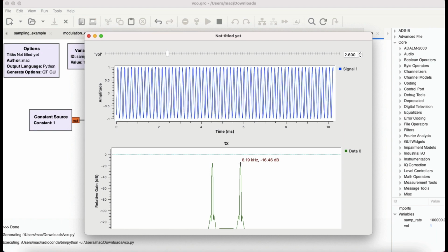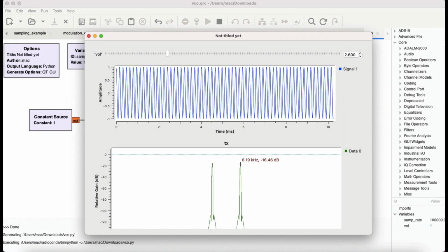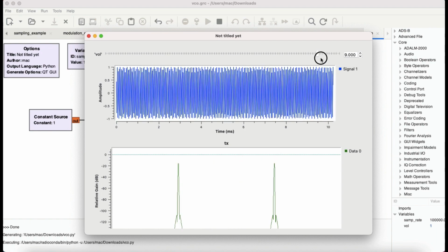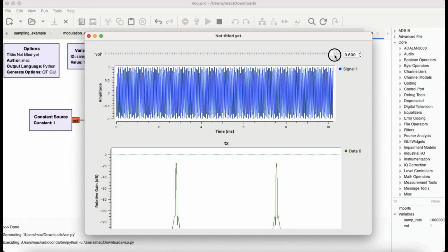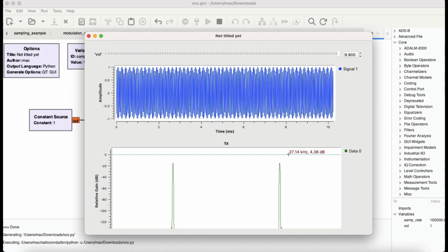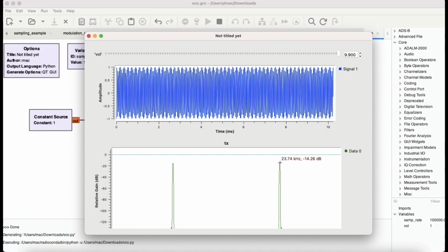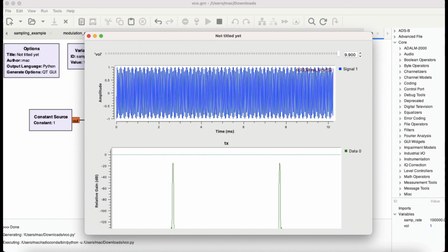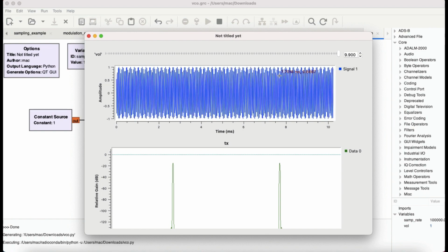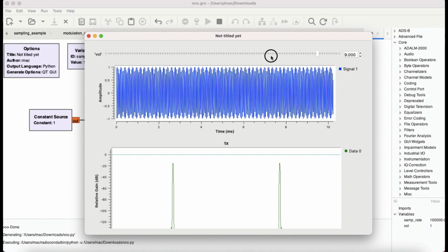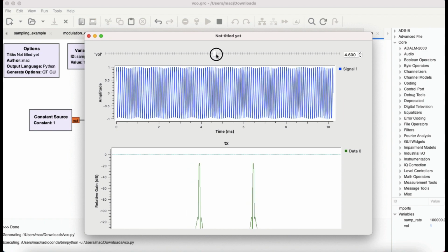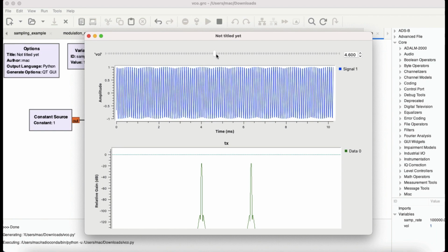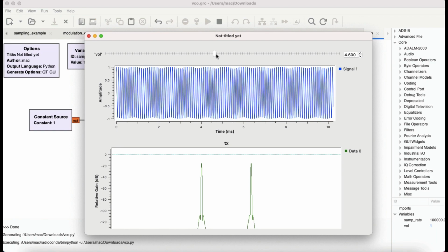So I'm generating at about 2.6 volts. It's giving me about 6.19 kilohertz of frequency. As I increase my voltage to about 10 volts, I'm getting somewhere around 23 kilohertz of frequency. Even though my signal is being compromised, you can see a change in amplitude, but that's the basic idea behind a voltage controlled oscillator. Once you change your voltage, you will generate a corresponding change in frequency.